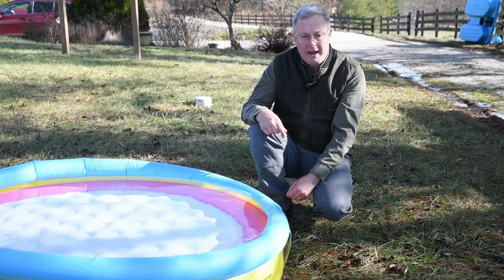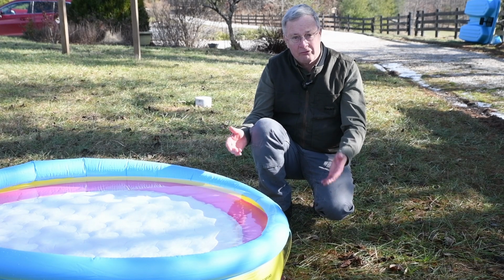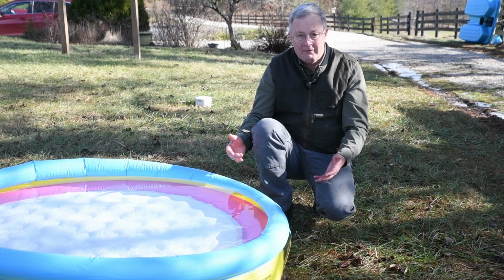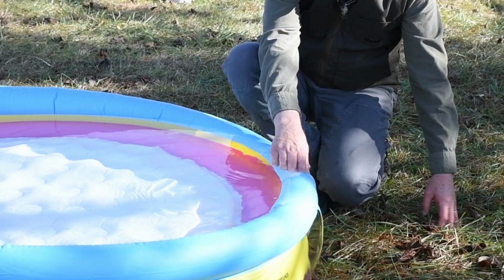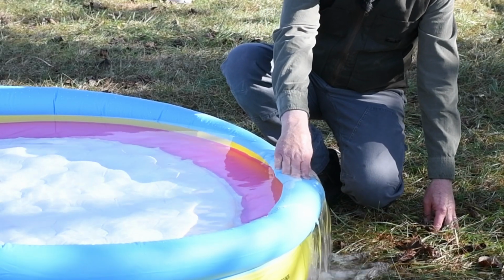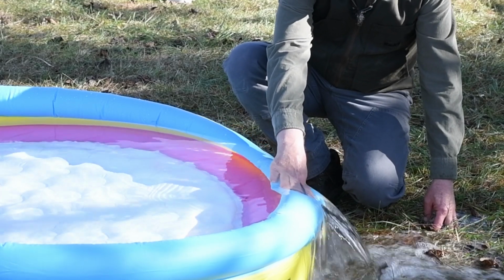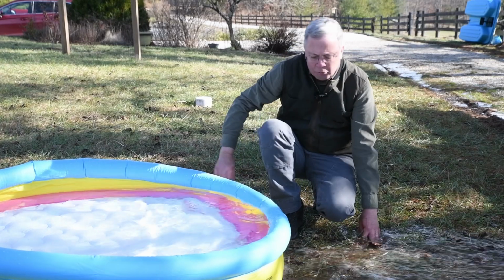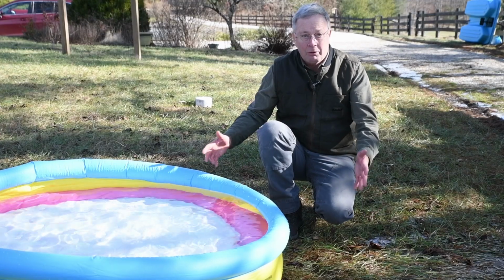Now, if you built a dam, you need a spillway. You don't want water going over the dam. It'll cause tremendous erosion. Here's what happens when you build a dam and you don't have an adequate spillway. It starts cutting a channel, you get head cuts forming, and pretty soon you have a torrent of water coming over that edge. And the head cuts will advance into the wetland pool and drain your entire wetland. This is why you need a well-designed and built spillway, so you don't have erosion.